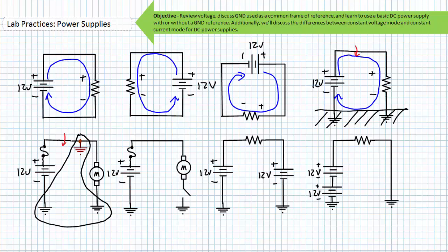Yes, with a 0 ohm path, current would spike to an incredibly high value, but this negative effect is handled by our circuit protection device, the fuse. When current in excess of this fuse's rating is experienced, it simply melts and becomes an open switch, stopping current. Look at our motor. At no point did our motor ever start because of this accidental ground connection, because each terminal is hooked to ground, and no differential ever occurred across it.